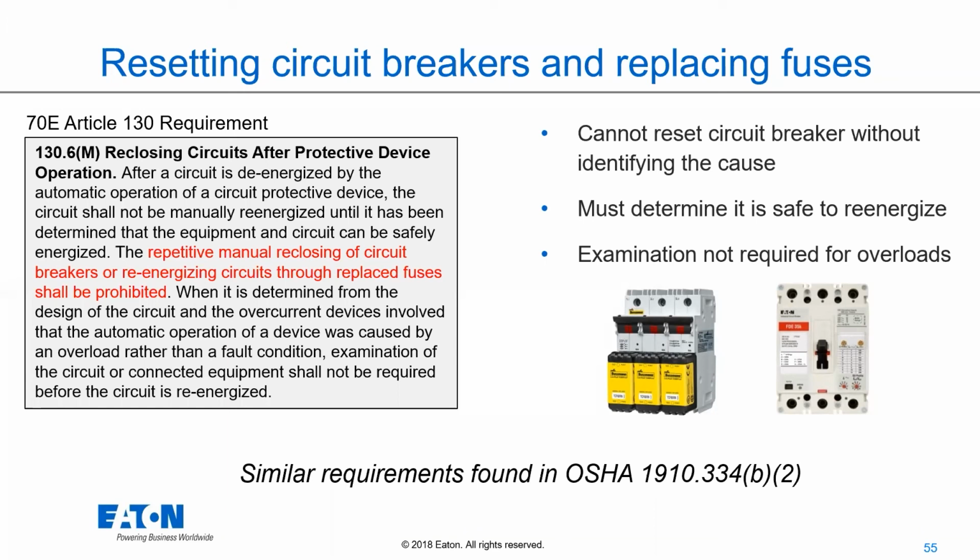So breaker trips, you say, oh, okay, I'll just reset it, and it trips again immediately. You reset it again, trips again immediately. That is not a safe thing to do. You want to determine that it is actually safe to re-energize before you turn that circuit back on. This goes with fuses as well.